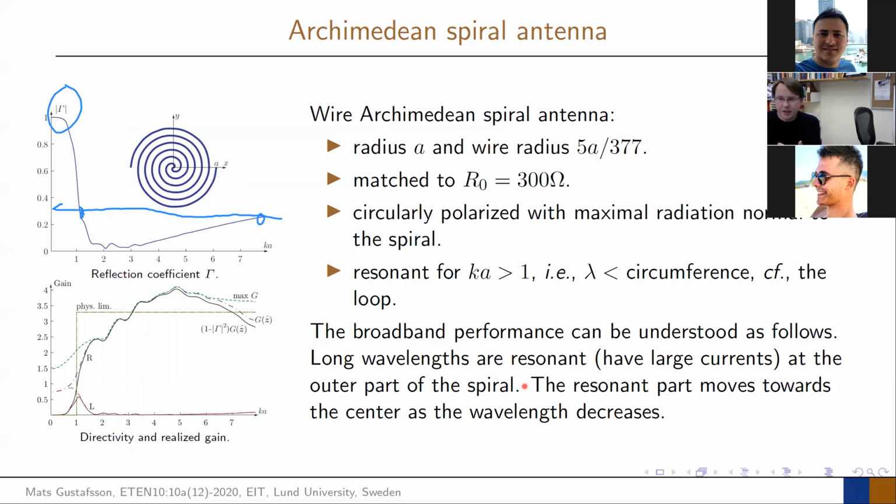But as we explained when we talked about the spiral antennas, they have a problem that they radiate up and down, so they're hard to attach to something. The lowest frequency where this works can be attached to the resonance of one loop. The circumference of these is in some ways the lowest frequency where you can use it. If you go to a higher frequency, you can find a loop that sits here, and you can make that resonant, and so on. That's why you create so many resonances, so in some ways there are almost no resonances. It's just broad. So that is one broadband type antenna.